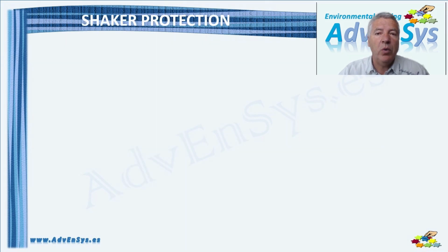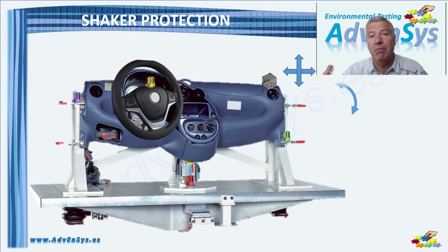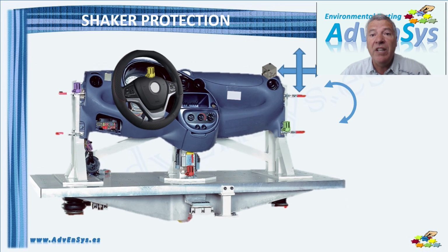Overturning moments is something we must always have in mind during our vibration tests due to its intrinsic risk to damage our system. Overturning moments can happen not only due to the excessive vibration in the testing axis, but also in cross-axis. Placing a limit channel, or better a triaxial accelerometer for three channels in formation, in a potentially highly resonant point and far from the center of the armature will protect our shaker, not allowing the test to reach a level that, multiplied by the affected mass and the distance to the testing axis, would mean an overturning moment too high for the shaker guidance system. This maximum overturning moment figure should be found in the shaker manual.